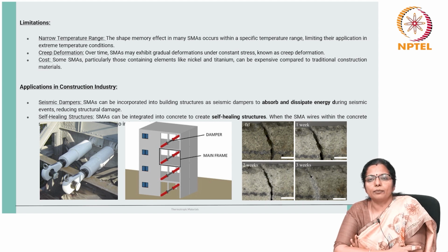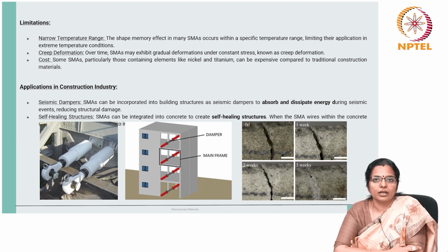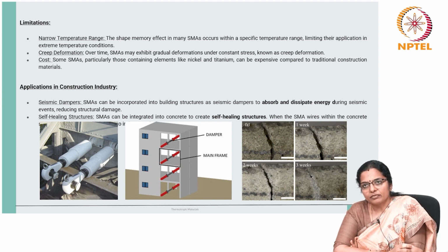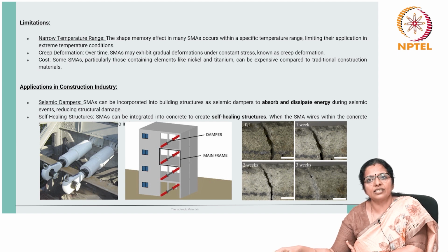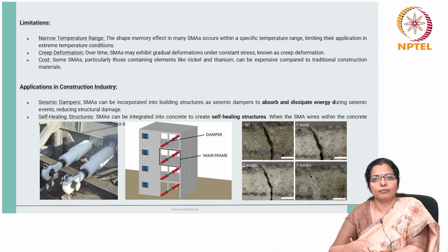Let us now look at the limitations. Now, narrow temperature range. The shape memory effect in many SMAs occurs within a specific temperature range, limiting their application in extreme temperature conditions. There is creep deformation. Over time, SMAs may exhibit gradual deformations under constant stress known as creep deformation.